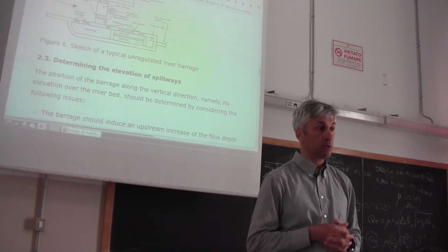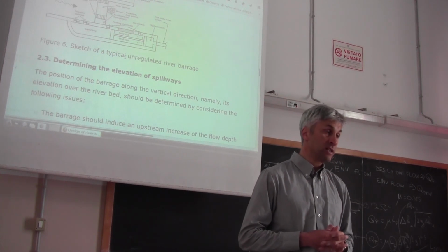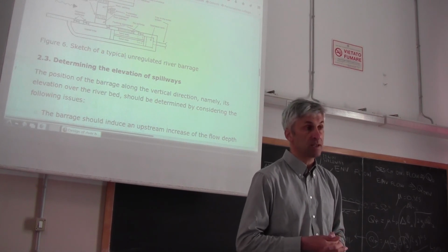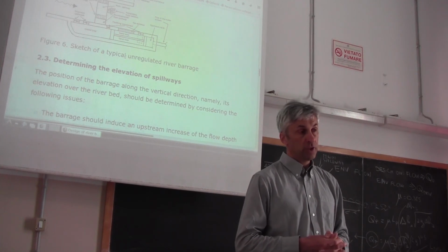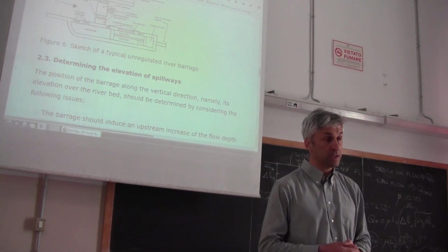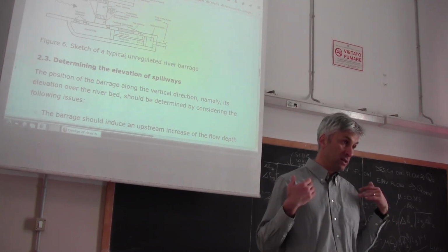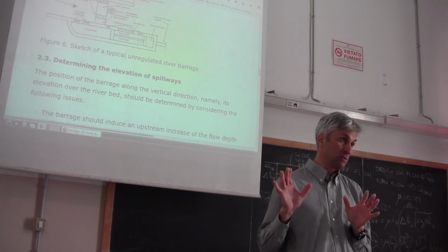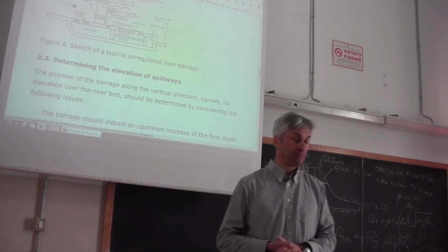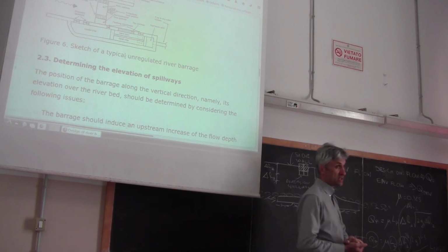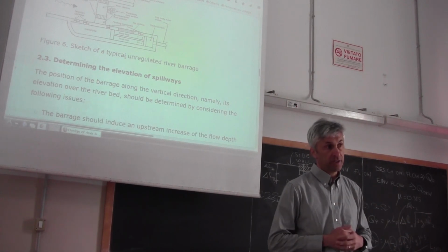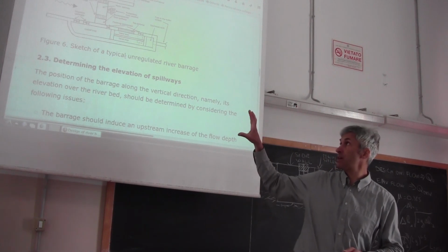And if you provide water to an aqueduct, you have laws in force that limit the concentration of certain substances, like turbidity. It's limited by law. And therefore, usually you have prescriptions given by the producer or given by the law in force that limit the amount of material that you can bring downstream through the diversion. So this is why usually when we have flows that pass a given threshold, we stop the diversion. But in any case, even if we divert water when the river flow is quite low, we have sediment transport in it and we need to remove it. So this is why we place a gravel trap and a sand trap.